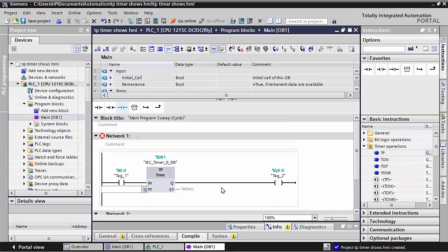and here I put 3 seconds time, I give the 3-second time, and here I use data register 1 for showing the elapsed time, MD0, MD0, and this I will download to the PLC.